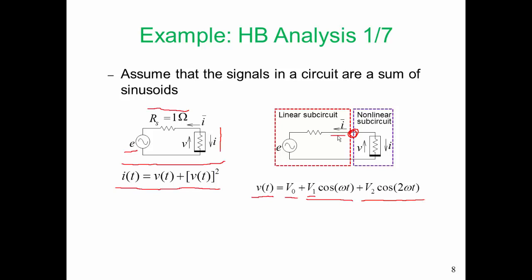I have a similar description for the linear current. It'll be comprised of 3 discrete tones, and a similar description for the nonlinear current. It will consist of 3 discrete tones. My next step inside the simulator, and I wrote this all in MATLAB, so these equations pretty much go directly into MATLAB. I then write a description of the circuit behavior in terms of phases, and here's the description of the relationship between the currents and the voltages in terms of discrete phases, and these phases are just scalars here because I've left out the phase.